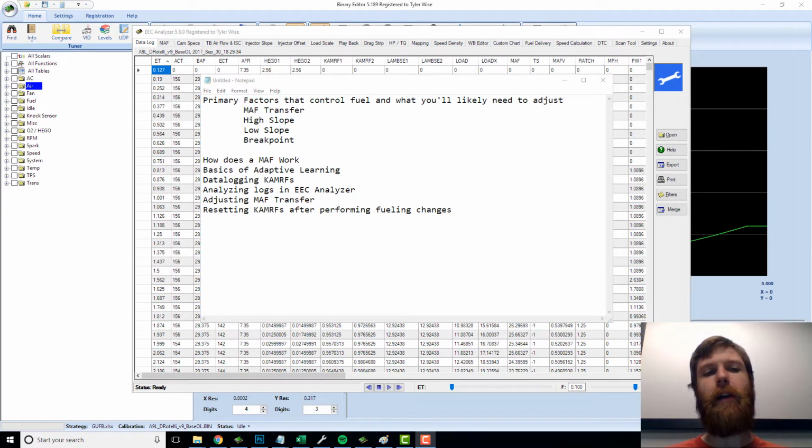So in this video today, what we're going to cover are the main things you'll adjust in your tune to get your fuel dialed in, which really comes down to your mass air transfer and your injector high slope, low slope, and break point, how a mass air transfer works and how your mass air meter works, the basics of adaptive learning, which is essentially your computer learning how to add or decrease fuel at various points in driving conditions so that it stays at the ideal air to fuel ratio, what things you'll need to data log in order to accurately take a look at that, what you'll need to adjust, how you can look at those logs in EEC Analyzer, and some tips on when you then load your next tune.